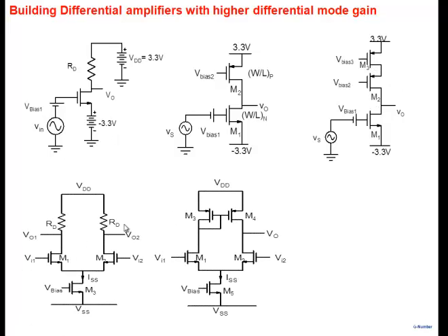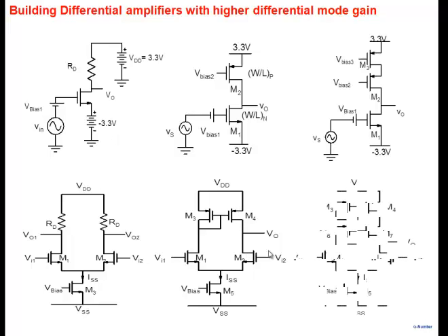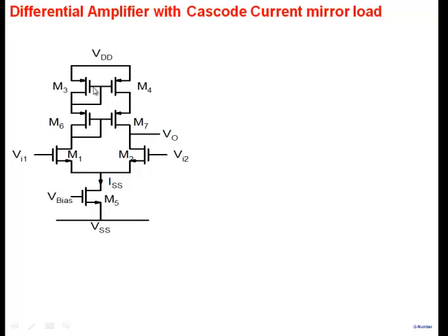Same thing you can think of here, as we have said: differential pair with resistive load, differential pair with current mirror load. If you're not happy with the gain here, what you do is just like you stack two PMOSes, you stack two PMOSes here. You can do that. Now you will see ICMR plus will bother you, because earlier there was a drop only from here to here. Now there are going to be two drops, so now it will begin to bother you.